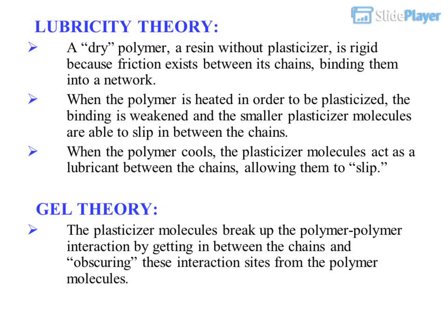Gel theory. The plasticizer molecules break up the polymer-polymer interaction by getting in between the chains and obscuring these interaction sites from the polymer molecules.